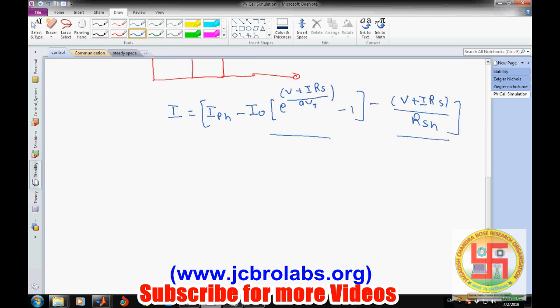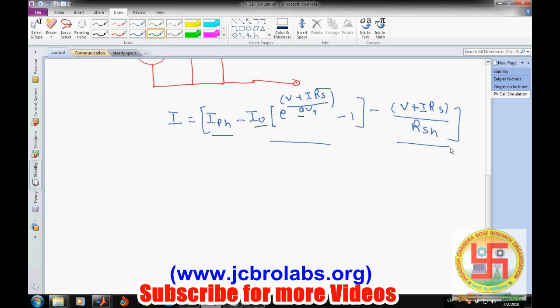Here we have several unknown parameters which play a critical role: what is this IPH, what is this I naught, the value of RS, the value of A, and one more value, which is the value of RSH. These are the 5 parameters which generally play an important role in the modeling of it: A, RS, RSH, and the value of I naught.